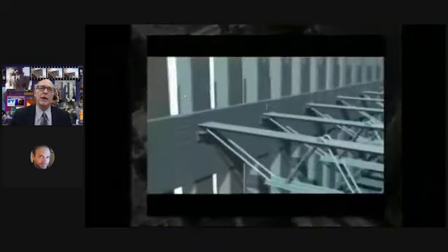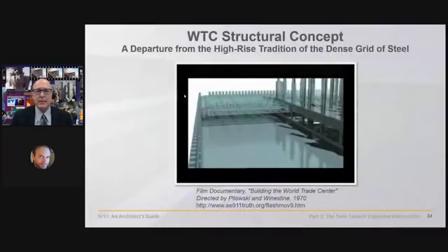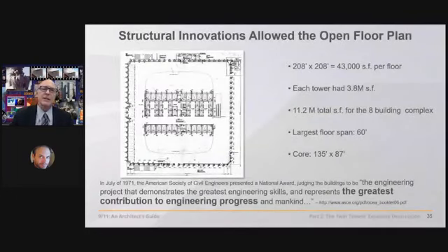Between these two structures, if you will, was laid the horizontal diaphragm, or the floor system, with concrete poured over these lightweight steel trusses. So this is where NIST focuses its investigation, as we'll see, on the vulnerability of these lightweight steel trusses. But design-wise, what that allowed is 60 feet of open office planning on the top of this side of the hoistways, and then on this side, and then 35 feet on the sides.